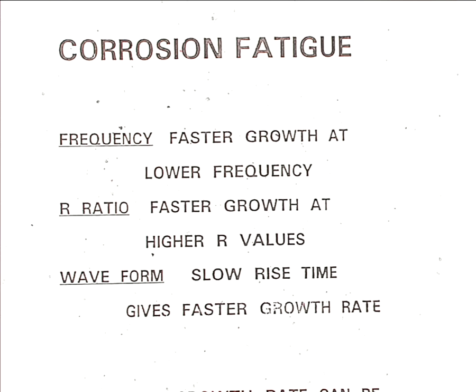So, anyway, it's all about the solution flow in the crack, okay? Because the crack is going to open, the solution's going to go in, it's going to cause some corrosion, and then the crack's going to close and the solution's going to be ejected. Maybe not all of it, maybe the crack is still open slightly at the bottom end of the cycle, it might not be hitting closed, depends on the application. But the solution flow has an influence, and therefore the frequency has an influence. And the waveform, in fact, the rise time, how quickly the crack opens, has an effect as well.